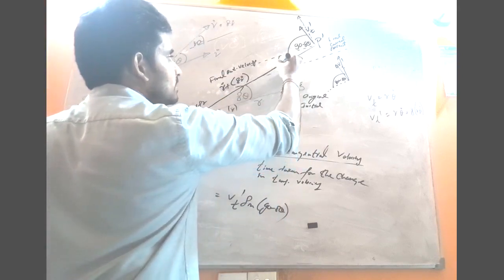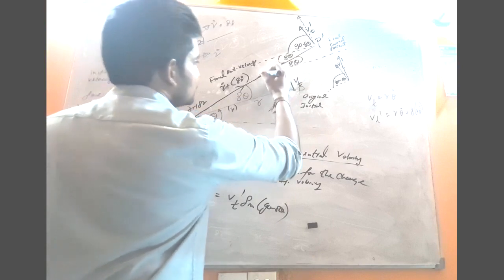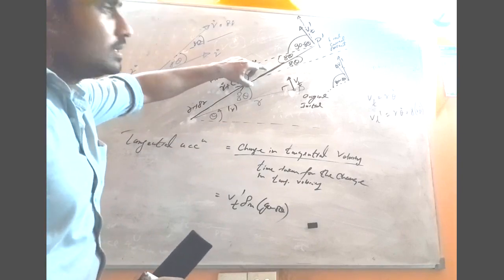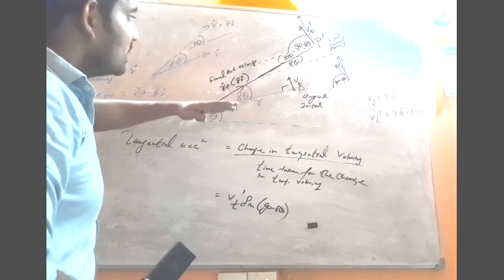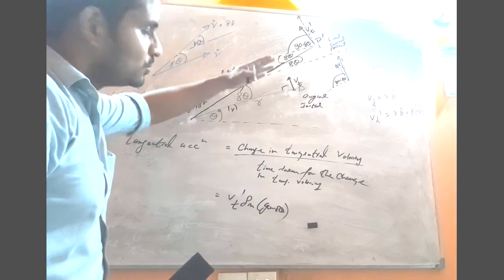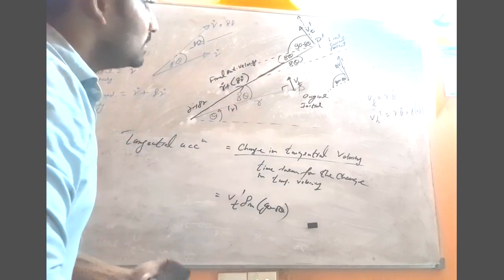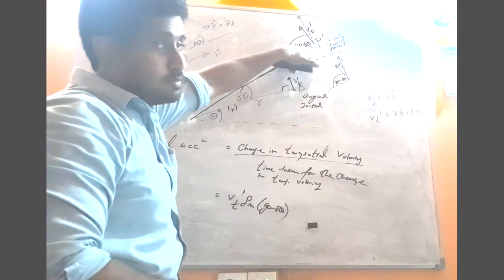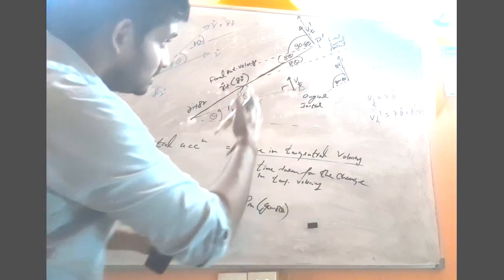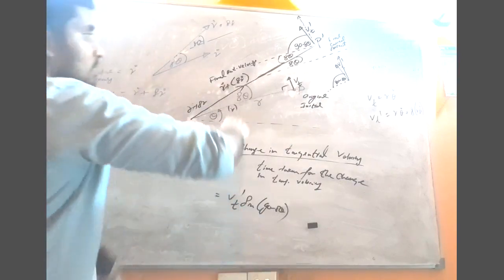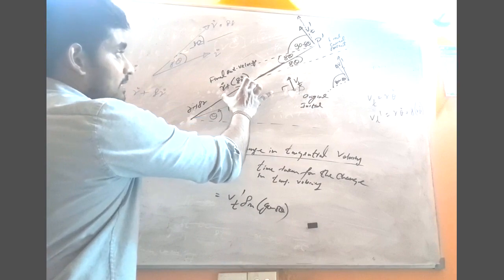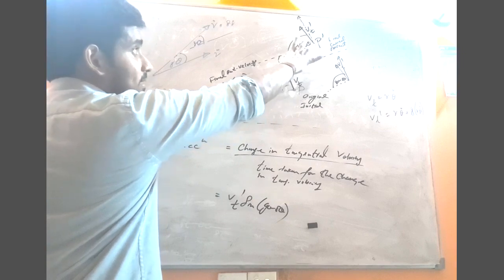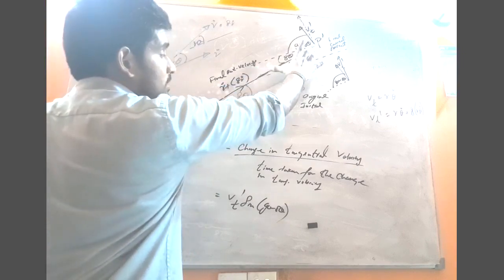So now this line represents the direction of the radial displacement of the present position, and the direction of the radial velocity of the present position, both are same, right? So then what is the component of the radial velocity of the present position that affects the direction of the tangential velocity? That will be r dot plus delta r dot times sine delta theta, right, towards the upward direction, right?